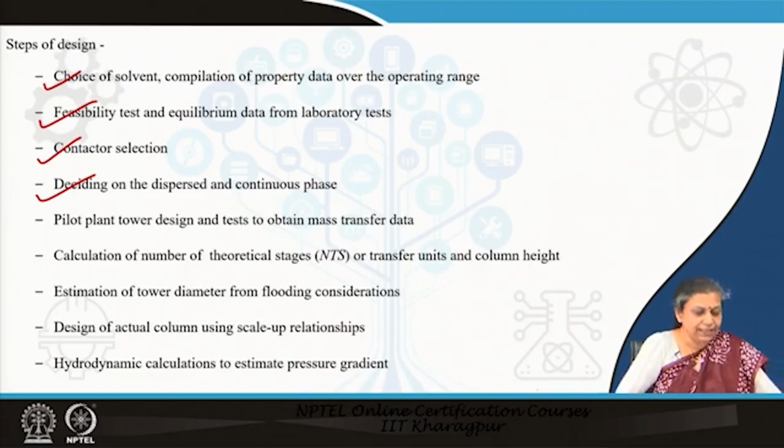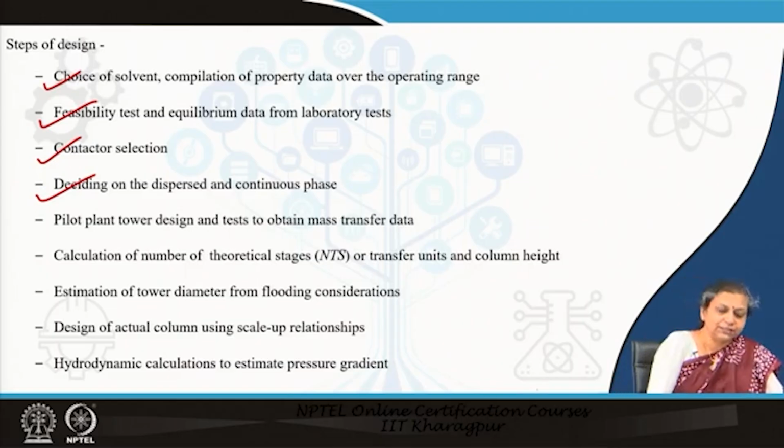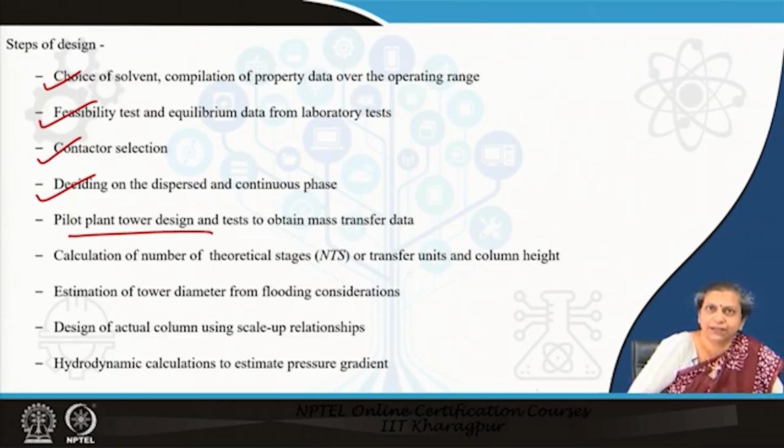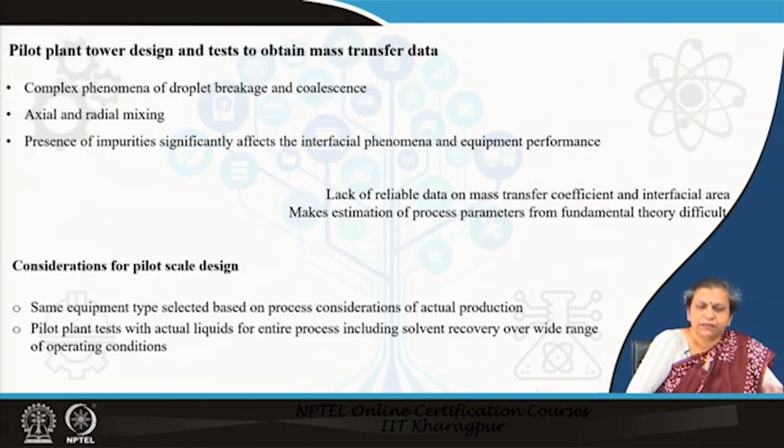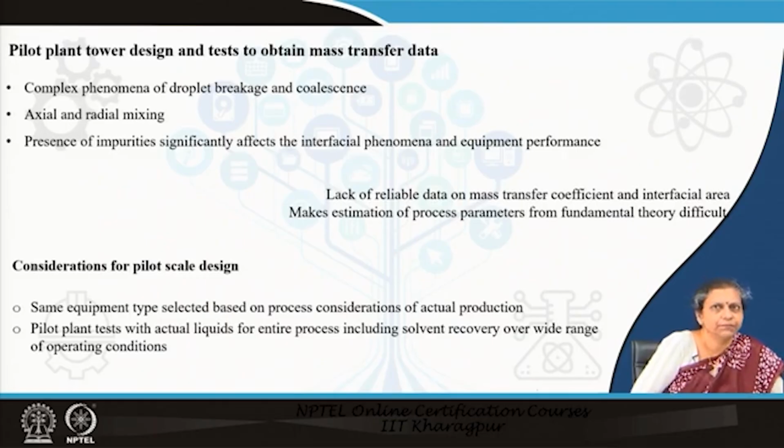Now, after this, the next thing which is very important is the pilot plant design to obtain the mass transfer data. For mixer settler, if you remember, I had derived the basic equation for the holding time. We found that the holding time was a function of mass transfer coefficient and interfacial area, and I had also mentioned that in this case there are a large number of uncertainties. Why?